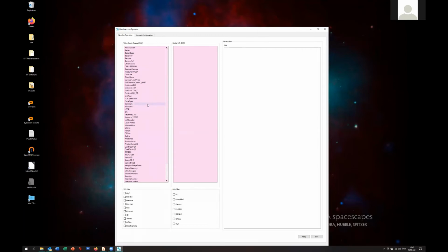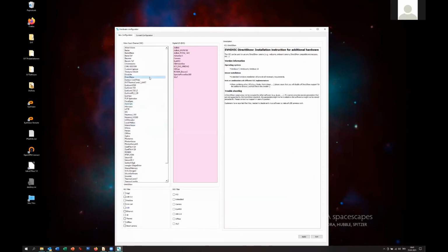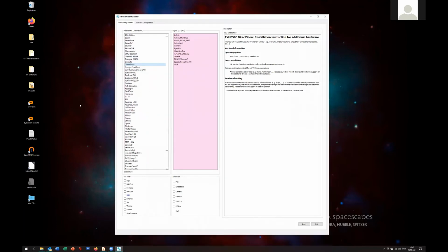Of course, if it's GigE, you can also use our GenICam interface. Depending on whether you have Windows, you can also use DirectShow if it's a DirectShow-based camera, or with Linux, you can use the Video for Linux interface. If you want to test mostly 2D, or if the driver is anyway installed, like if you use, for example, RealSense, it's automatically grabbed from the main website from Intel, and you can use it directly.